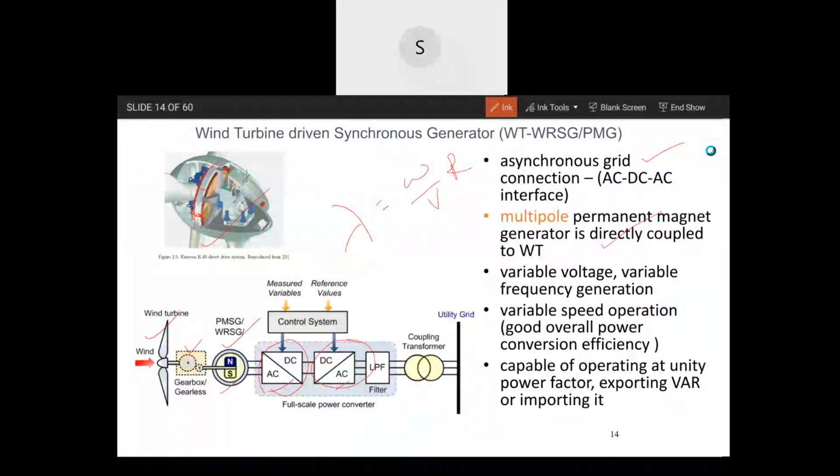So the main advantage is increase in efficiency. An additional advantage is that your nacelle size is reduced. You have a simpler system, and the operation will all be convenient. Of course, there should be some inertia on the tower top. If very low inertia, that's also a problem. But anyway, the gear is not there, so you can couple it directly. Simplicity. The number of parameters in SCADA can be reduced when the gear is not there.